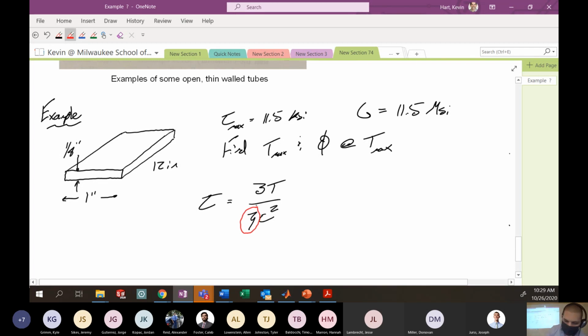Here it's the median line length, so we can draw our median line in here. In this problem, it's pretty easy to see that zeta is going to be 1 inch. For L brackets and Z brackets, it can be a little more confusing when you're calculating some half thickness as you go around a bend. But this, just a flat piece of material, is pretty easy to see.